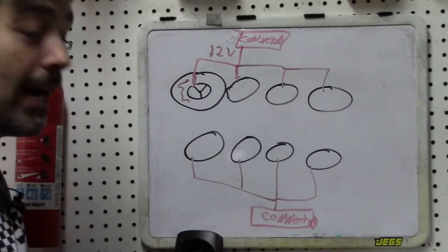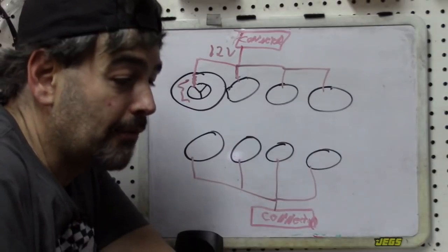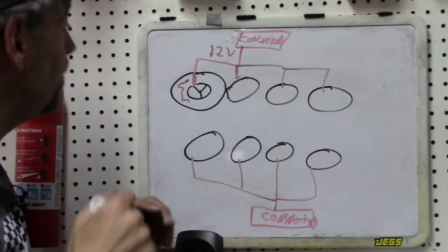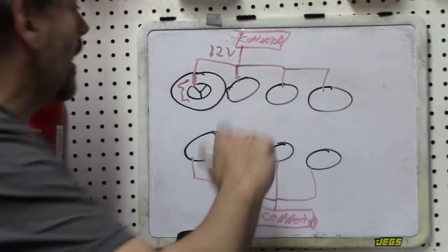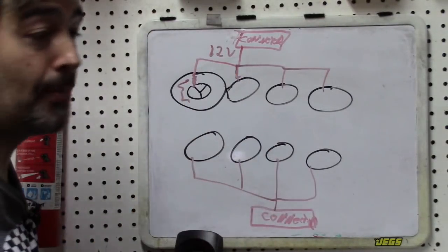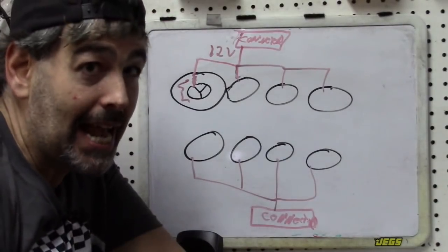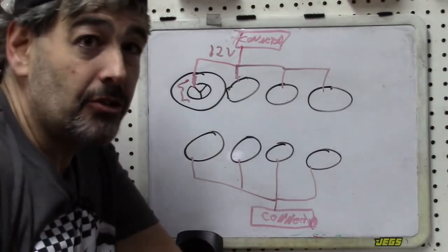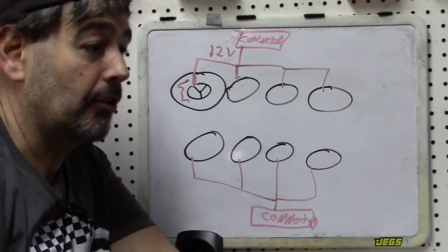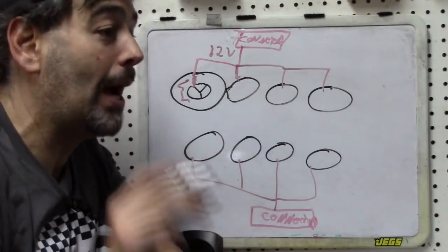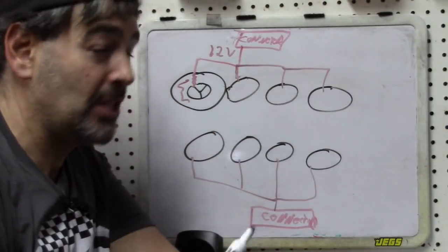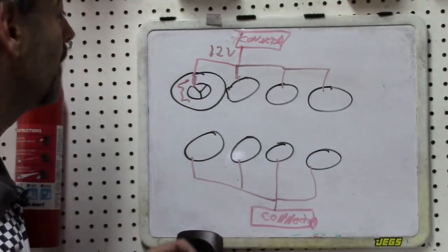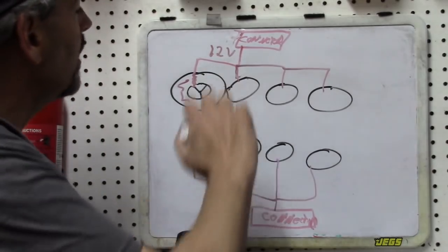Okay, we also had a green and a black wire, I remember. One of those, again from experience, I'm going to assume it's the black wire. Could be different. Either way, this diagram is going to be correct. The wire colors may not be. That's why I need to validate so that I can actually check the wire colors. The wire colors, I'm not interested in. I'm never interested in wire colors. I'm interested in wire function. Wire function is what you look at when you know what you're doing. Wire colors are what you do when you're still painting by numbers, which we're not doing here. We're understanding this. We're doing this by function.